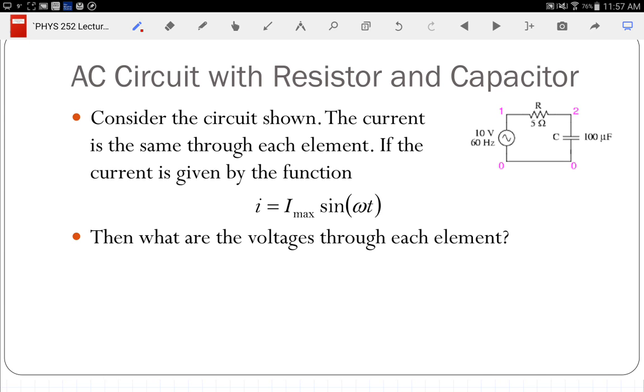They are in series, so they have the same current everywhere. And so I have I_R, which is V_R over R, equal to I_C, which is C dV_C/dt. Make sense? They have to have the same current.